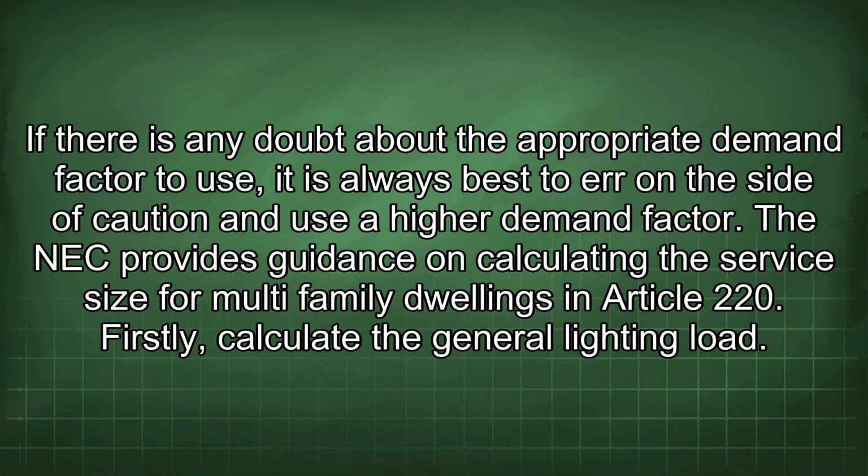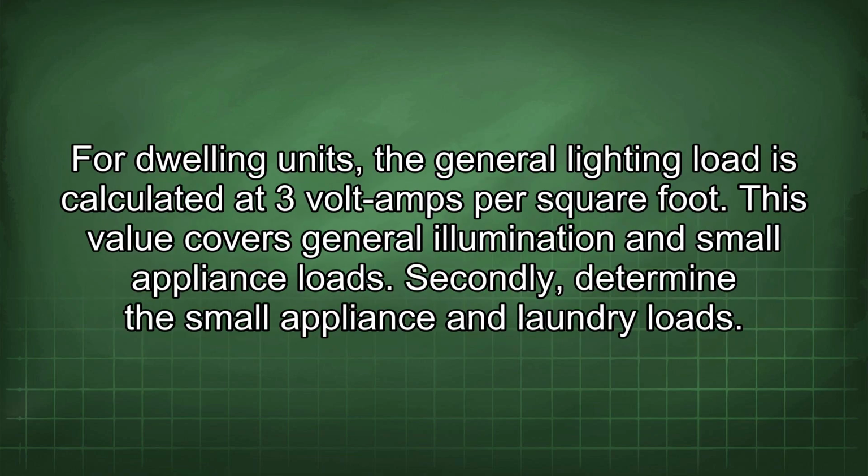The NEC provides guidance on calculating the service size for multi-family dwellings in Article 220. Firstly, calculate the general lighting load. For dwelling units, the general lighting load is calculated at 3 volt-amps per square foot. This value covers general illumination and small appliance loads.